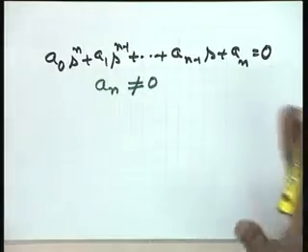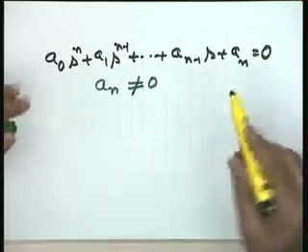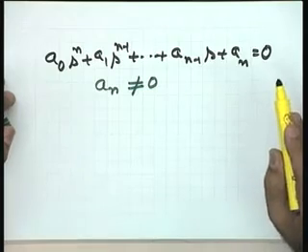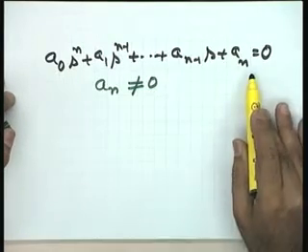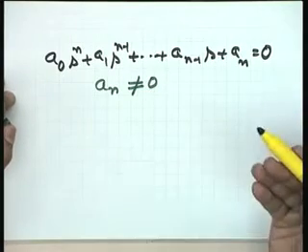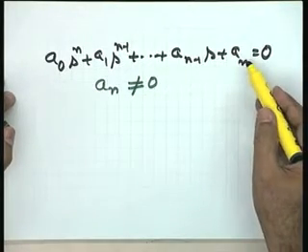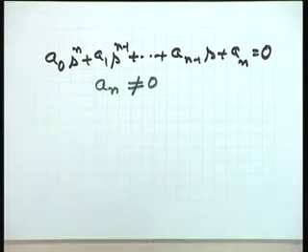So, I am assuming that in this characteristic equation, a n is not equal to 0. So, if a n equal to 0, you take out the root at s is equal to 0 and reframe your equation, so that the last coefficient of this particular equation, which is the coefficient of s to the power of 0, should be non-zero.